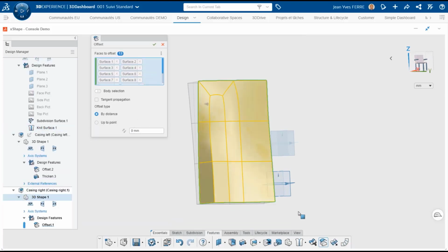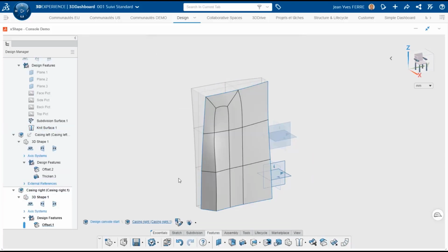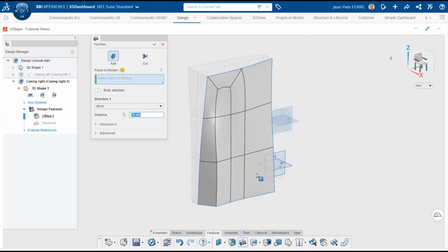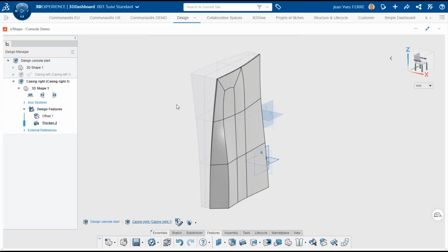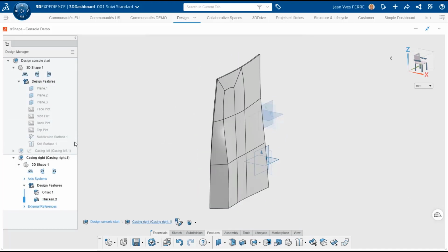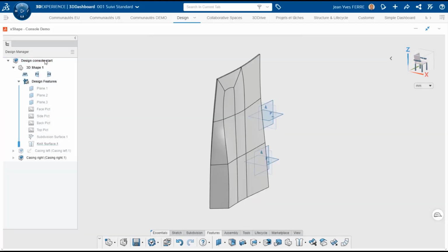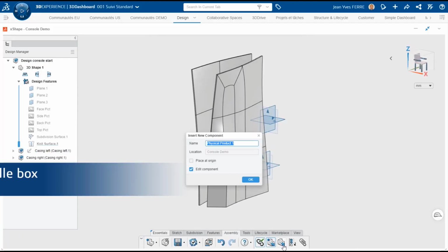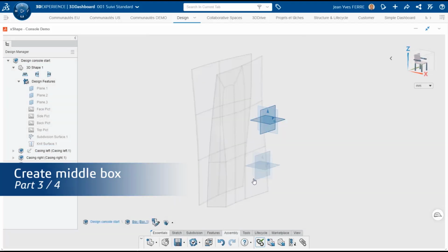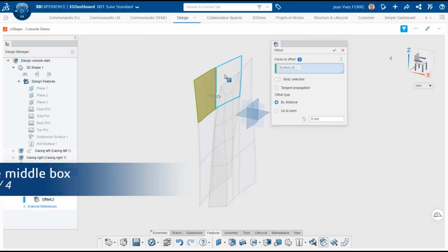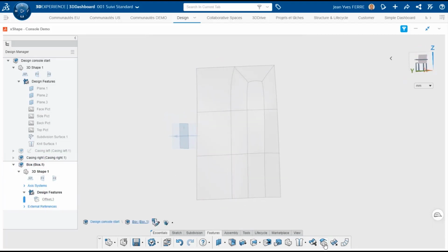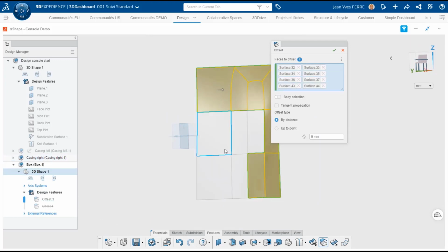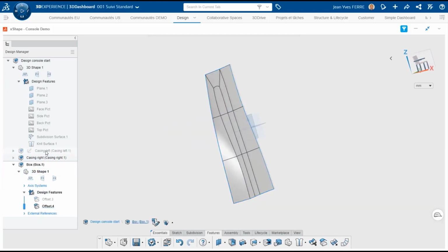Here, we will create a part for each side of the console. We copy the faces inside our part and add thickness. We do the same for the other side. We need to create a box in the middle that will contain all the electronic components. It fits exactly between side components, so we collect both surfaces and use them as end conditions for the extrusion.